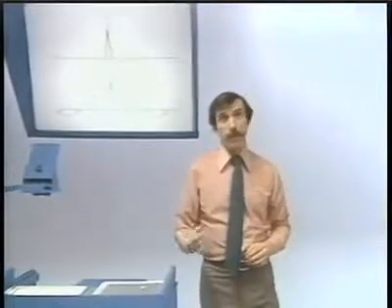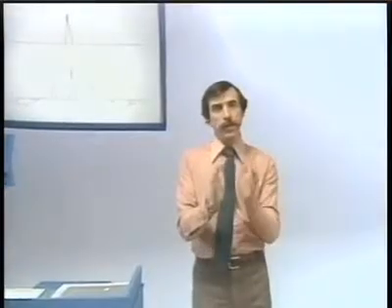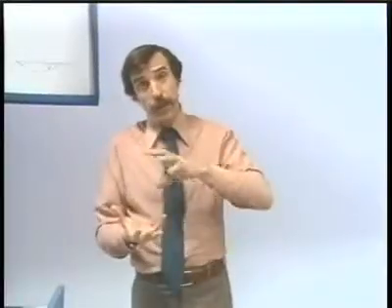It really is amazing that all this depends on is the original signal being band limited and the frequency of the pulse train being high enough so that when you replicate the spectrum in the frequency domain, there's no overlap between these individual replications. And we'll address that a little more in a few minutes.